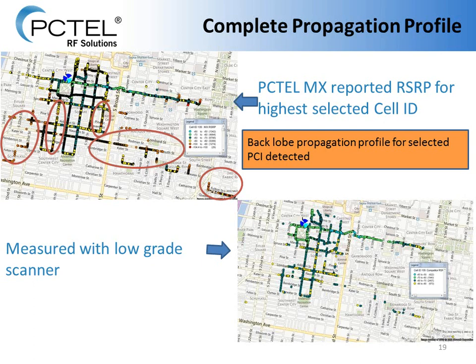It's quite dramatic. We're getting a lot more detections with high dynamic range to find out what's actually propagating into these sectors versus what a low-end scanner is able to provide. And we can even see the backlobe propagation coming off the antenna with a high dynamic range scanner, to find out what's really happening in that RF environment.